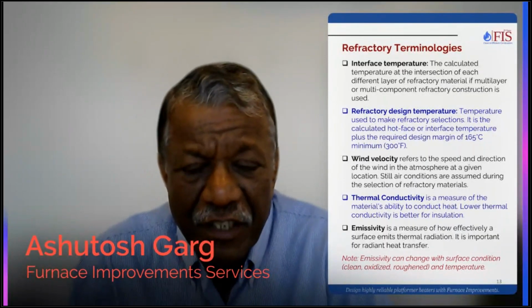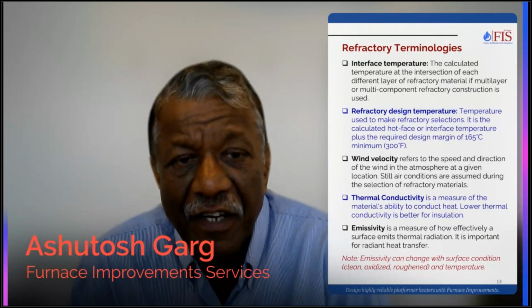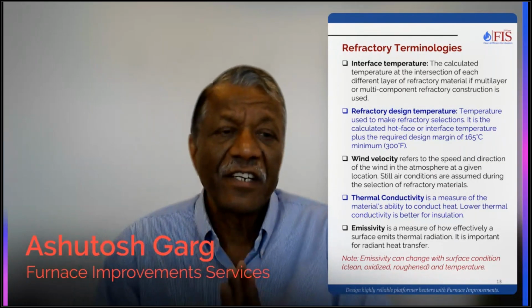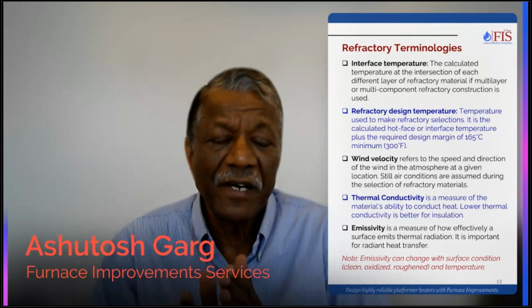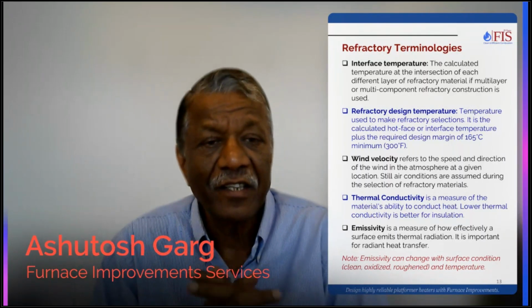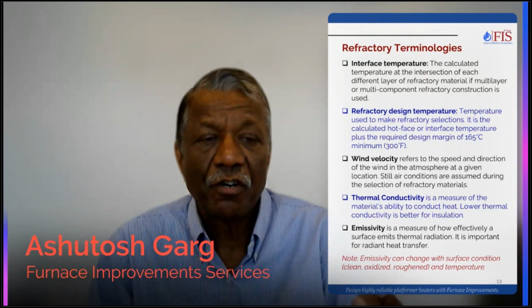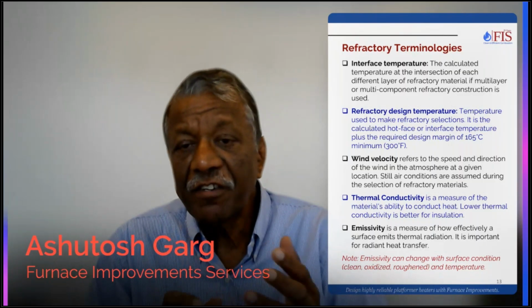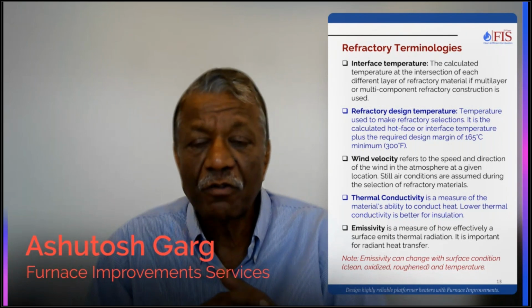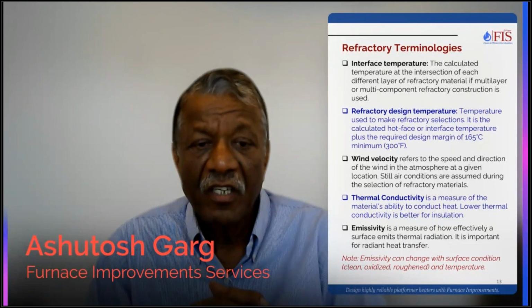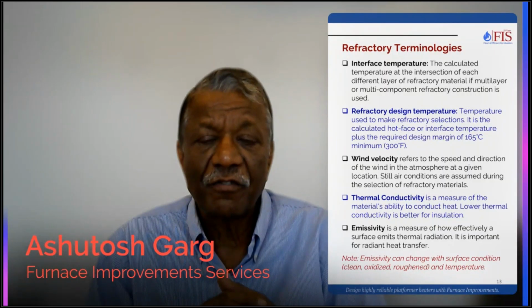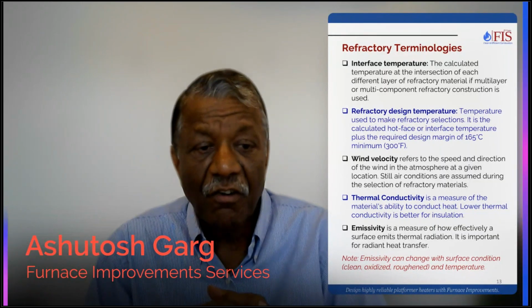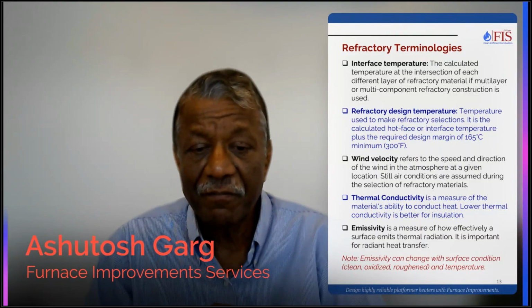Interface temperature is the temperature between two layers of castable or two different refractory layers. Then refractory design temperature. API says it should be at least 300 degrees higher than the operating temperature or your design temperature. That's how the refractory should be designed. Wind velocity also plays an important role in heat losses. Thermal conductivity, of course, is the most important parameter. Emissivity is also important for heat transfer.